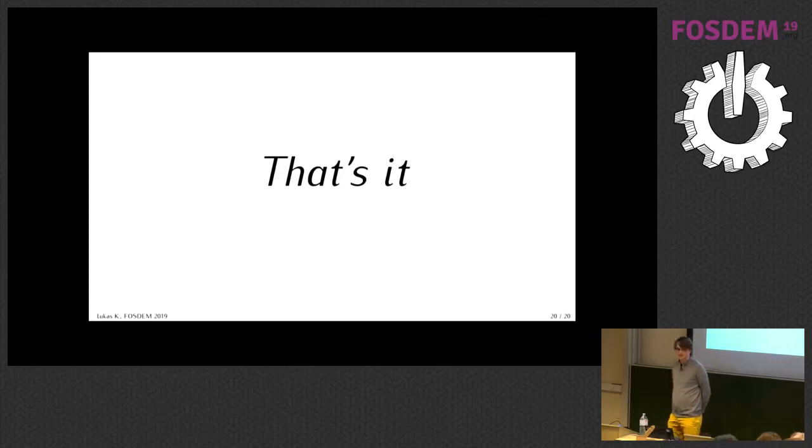Okay, so I guess the question was about design rules. Horizon supports something that is a bit like the rule system in Altium. You can have many instances of the rules. Each rule has some criteria that it matches on. For example, it can match either on net name, net class, or a regex that matches the net name. For clearance, you've got 2 matches, and if these 2 matches match, then that rule, for example a distance rule, will get applied. And that distance rule can specify the distance between track to track, track to wire, track to pad, track to board edge, or something like that.